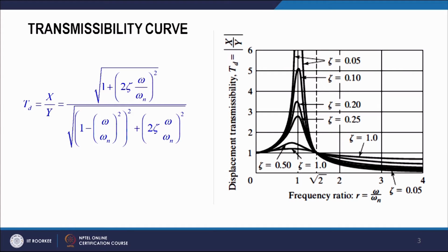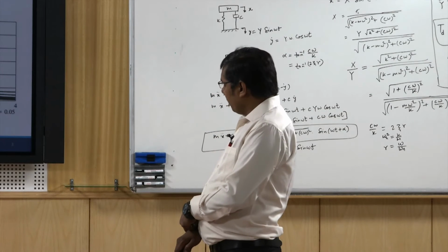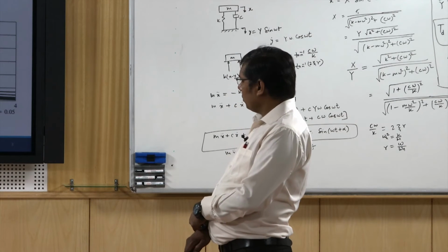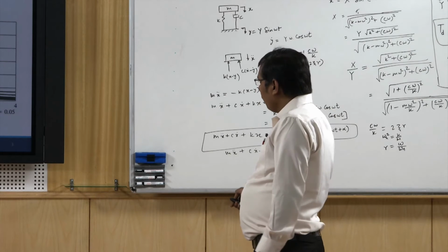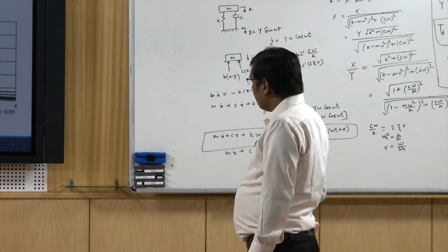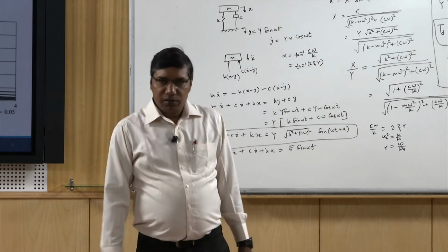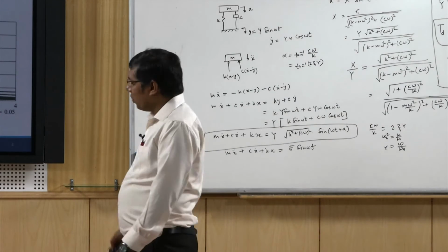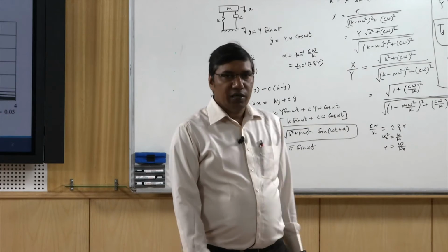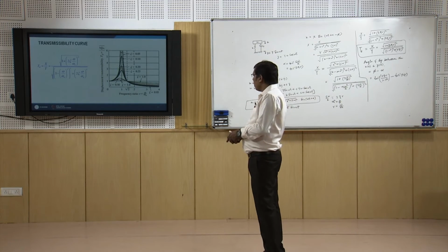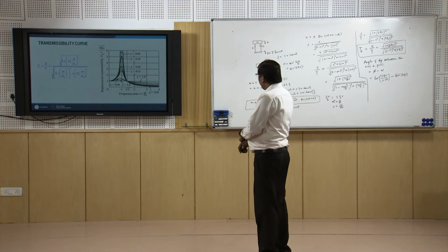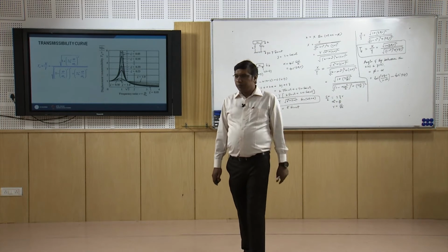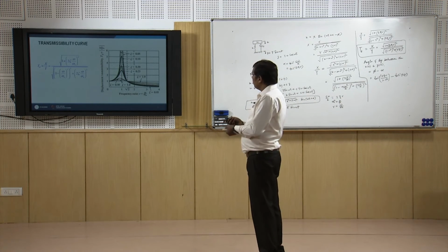So at root 2 it is again unity and goes to lower values of displacement transmissibility. And when we have r that is large, the transmissibility is lower. This is the region where we are interested, and as we discussed, this region is mass controlled, so we have to stay in this region for lower transmission of the displacement to our mass m.